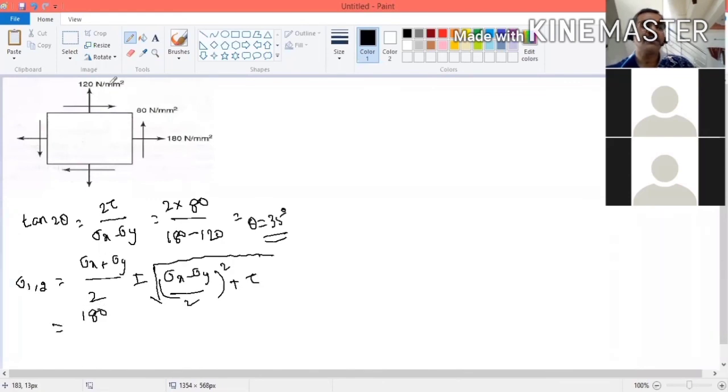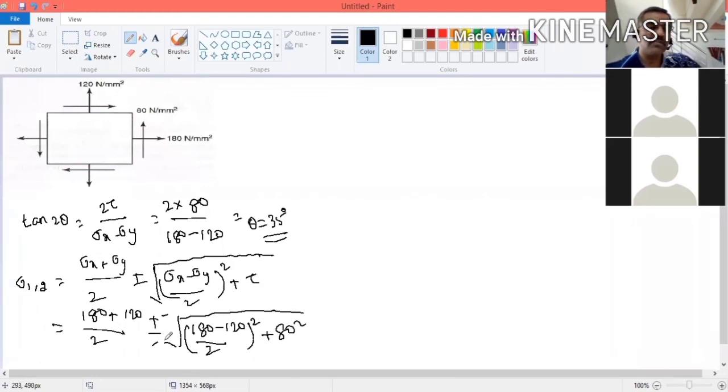Since all are tensile, you put plus. 180 plus 120 divided by 2 plus or minus root of 180 minus 120 divided by 2 the whole square plus tau, tau is equal to 80, square. If you put plus, you will get sigma 1. If you put minus, you will get sigma 2. You will get two values, sigma 1 and sigma 2.